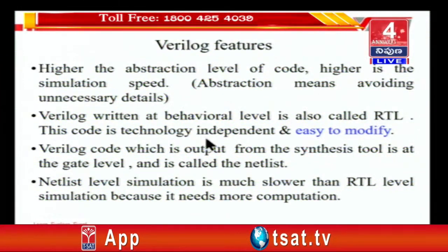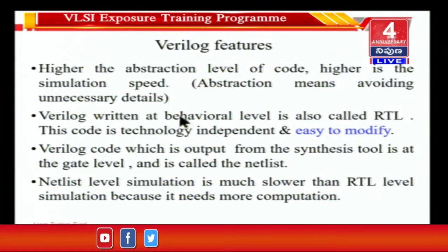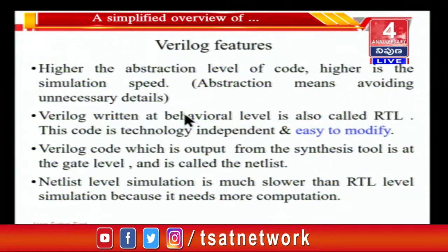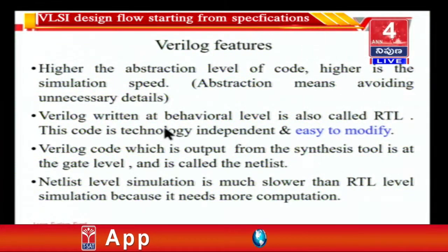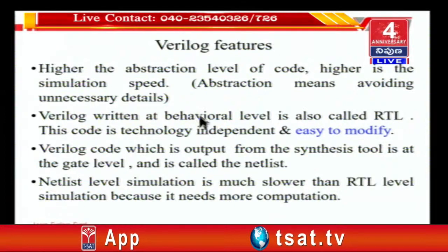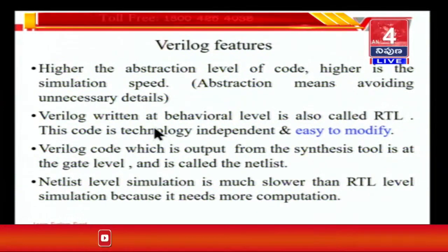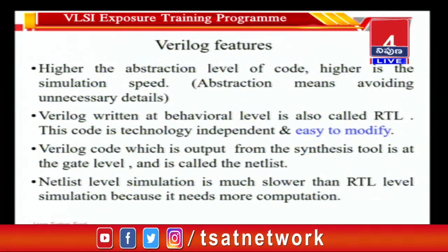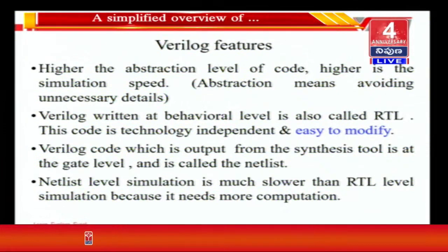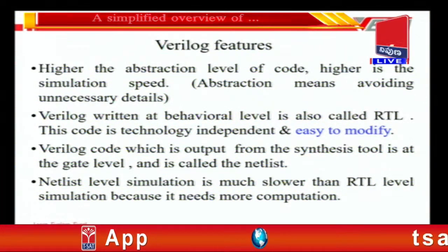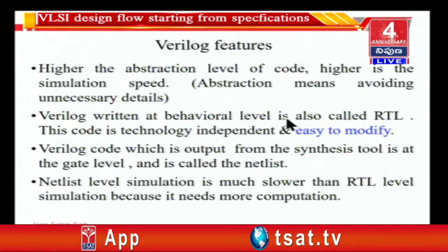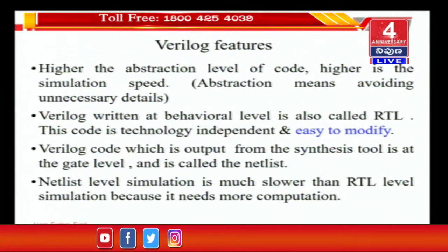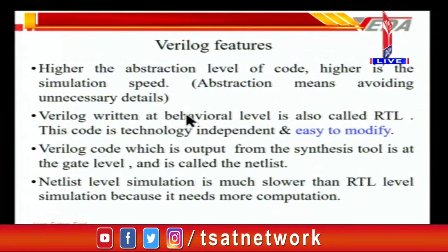This is technology independent. When I say technology independent, it means that I can take the same code and target it to make a chip at a different technology node with a different process node, because Verilog written at the behavioral level doesn't contain any technology dependent factors like the delays of the gates, the sizes of the gates, and anything. It is pure functionality. There is no timing involved. Okay, this behavioral code, the RTL, you can make it operate at 1 gigahertz or 10 gigahertz also by just having a clock of that particular time period. That's it. You can make it work.